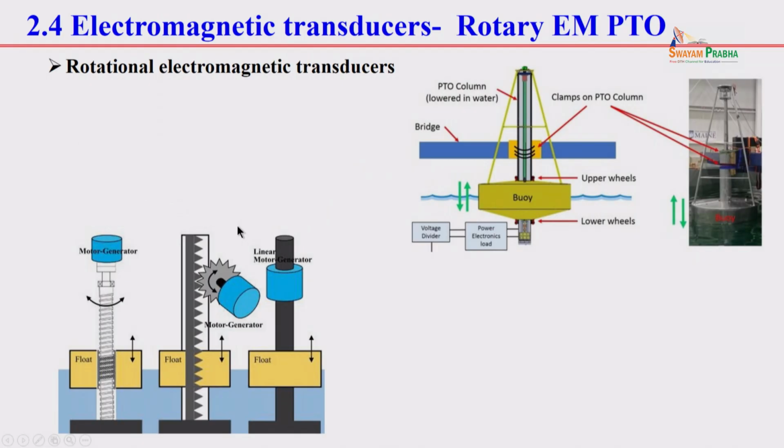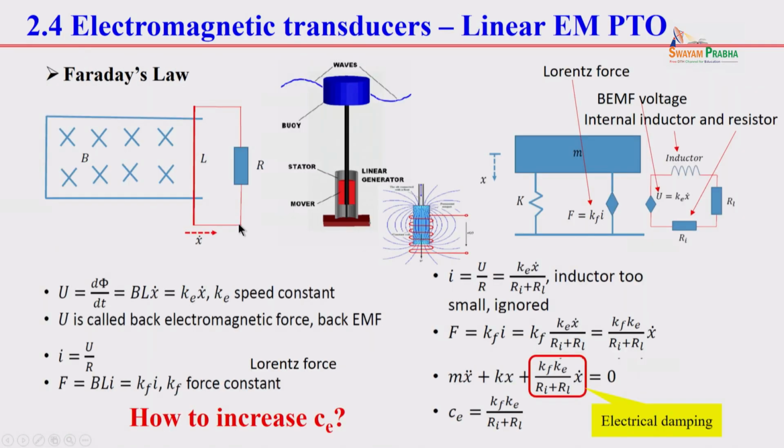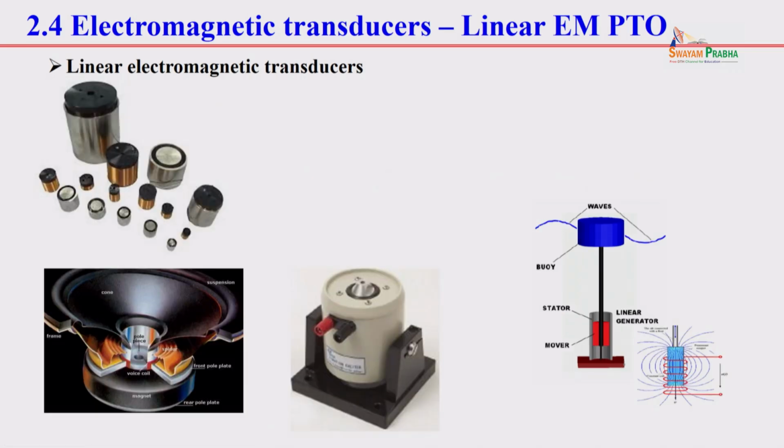For this type of thing, like I show you here, you give current, you can drive the system, right? This becomes a motor. And if you have a resistor load, this motion can directly drive it, and that is a generator. For this type of system, DC motor and DC generator are the same.